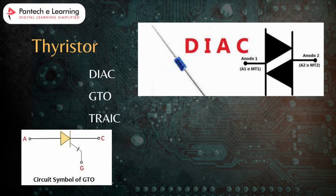So this thyristor has one control gate that acts like a switch. When a small control signal is sent to that gate, the thyristor turns on and allows the electricity to flow through. Once it is on, it stays on until the current drops to zero or another signal turns it off. So this is the thyristor.